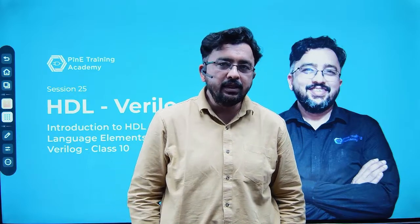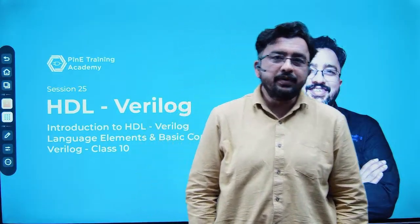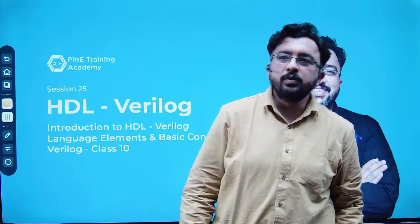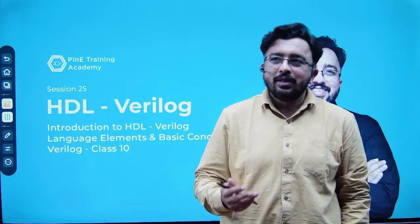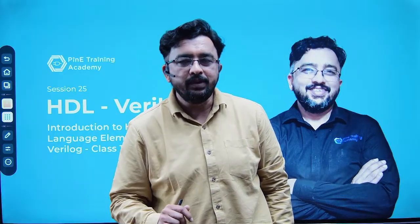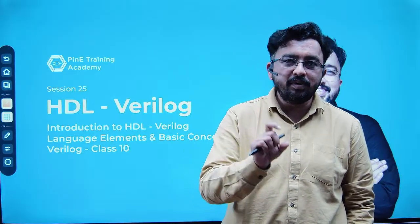Today, my objective is to cover the vector part. Vector is a very important data type, and it is very commonly used in Verilog. If you don't know the basics, you cannot use it: how to declare it, how to use a single bit, how to use part bits, how to compare it, how to concatenate it, how to replicate it.